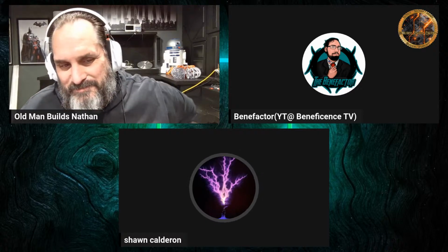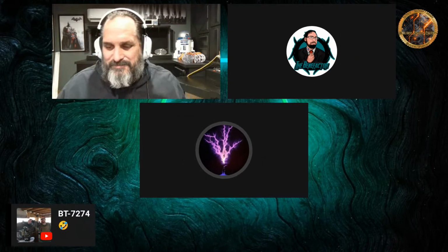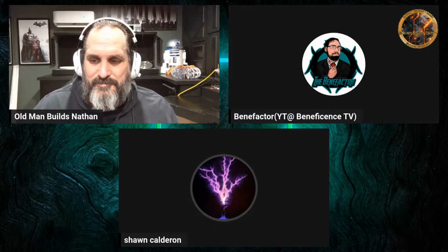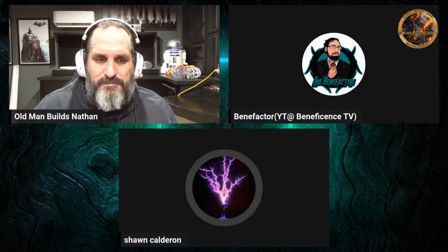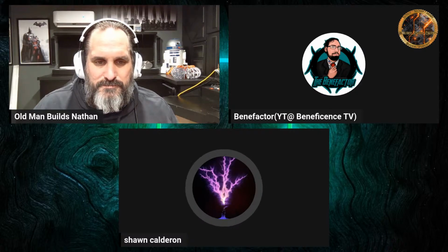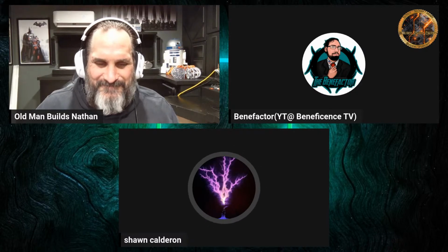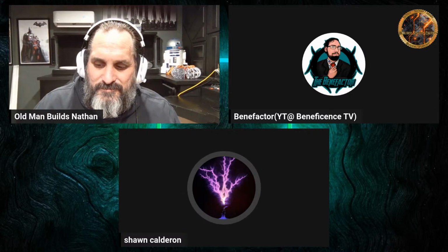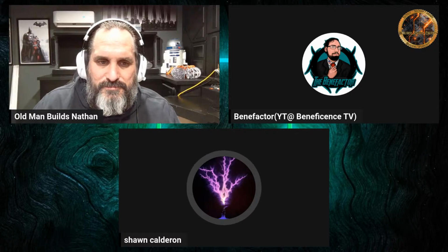David Gruel says if you run extra MOSFETs in parallel, it will reduce heat in your MOSFETs. Not really. Depends on what you're talking about. Definitely not in a Slayer circuit. I've tried it. I've literally soldered together MOSFETs in parallel to hopefully bring down the heat because it's given them more capacity. Nope. It'll fry 4 parallel soldered MOSFETs as quick as it'll fry 2 or 1. And I know that by experience. So it's great in theory, and I appreciate the comment. Unfortunately, it's just never panned out.